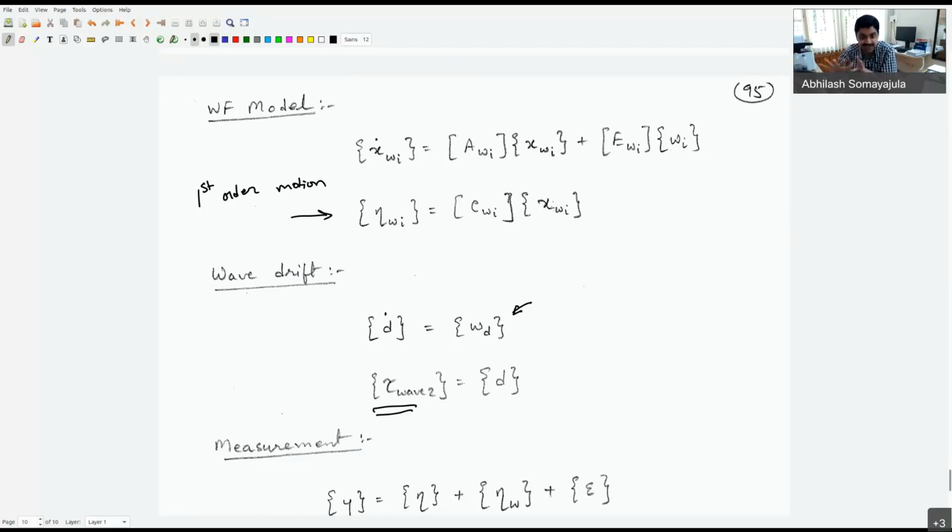Okay. Notice that this is not an exact model as we were doing with the first order wave forces, but it helps us get started on tuning our controller much faster than actually developing an accurate model for the dynamics. As long as we are able to deal with signals in the same frequency regime, whether artificially generated or really experienced by the ship, we will be able to account for both of them using the same controller. That is the main idea.